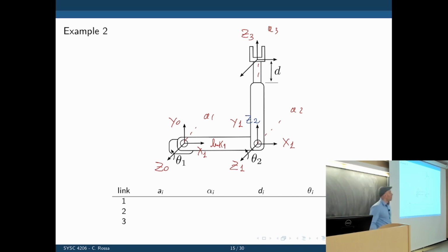Can you explain why it's in the C spot? Because now we are dealing with the next frame, which will be rotated and also translated. This frame has the ability to translate. We're changing the actuation axis from a rotation to a translation. So instead of going around here, it goes along the actuation axis of the next link.